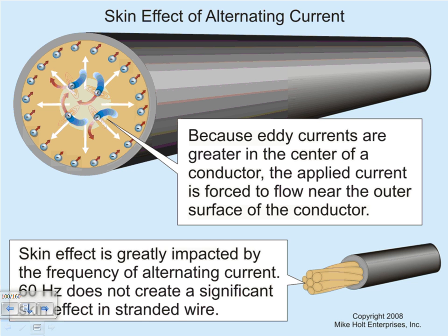Anybody can tell me why the core is steel? When they have a run of, say, 1,000 feet, the steel will hold the wires together in the air, for the physical weight. So the steel core inside is for carrying the weight, and the surrounding wire, the shell, will be carrying the current.